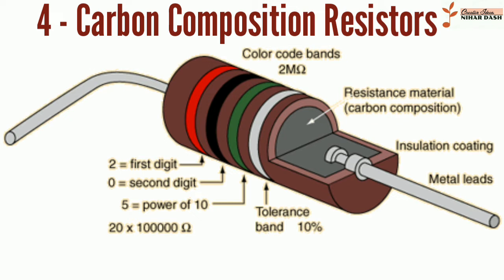These resistors are non-inductive, which provides benefits when used in voltage pulse reduction and surge protection applications. Carbon composition resistors have higher capability to withstand overload relative to the component size. Carbon composition resistors are still available, but relatively expensive. Values ranged from fractions of an ohm to 22 megohms.